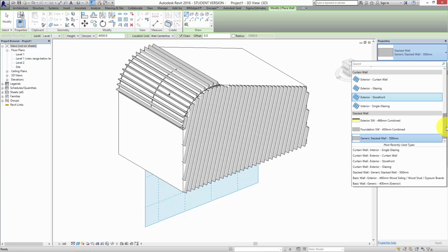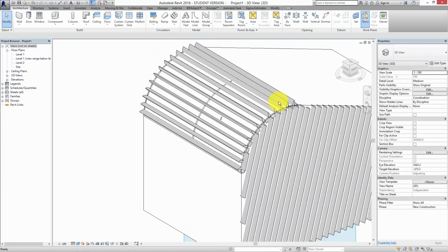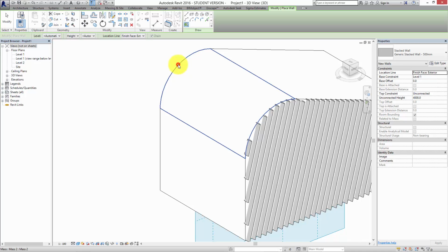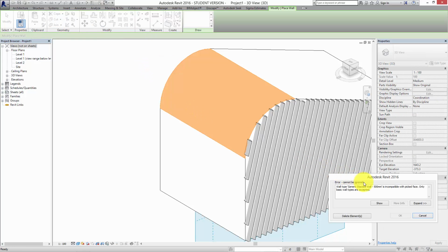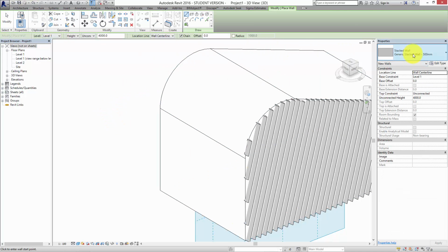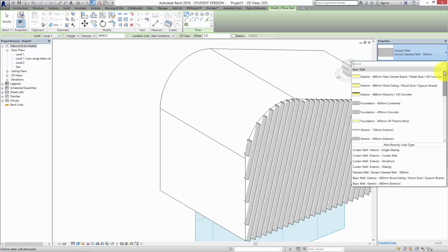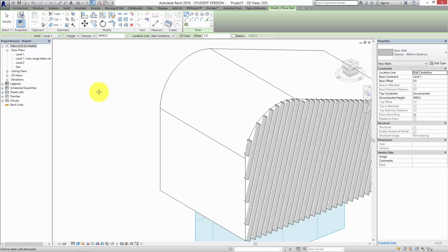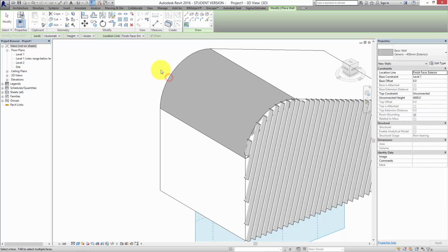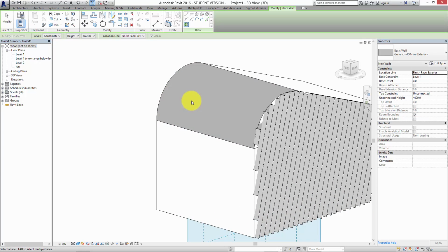It's okay in this building, but let's say, for example, I delete this. Let's delete this curtain wall here. And I'm going to say wall by face. I'm going to apply it to this face here. Oh, there's a too complex wall I've got set up, so I need to change the wall type first of all. Wall, just going to change it to a generic wall. So then I can come into wall by face, select, and it's generated a wall there along those lines.